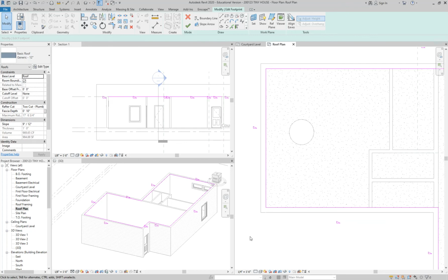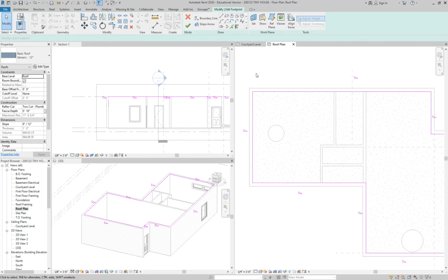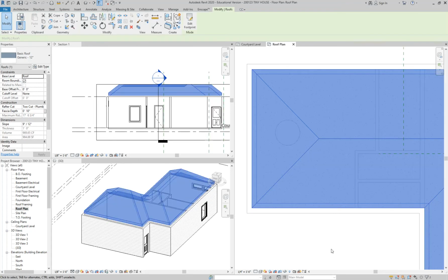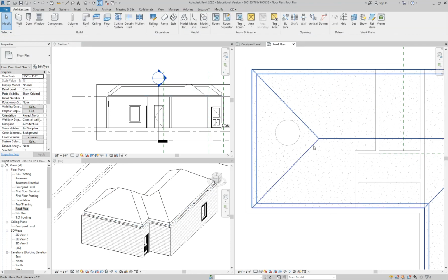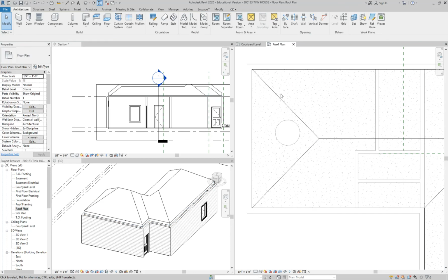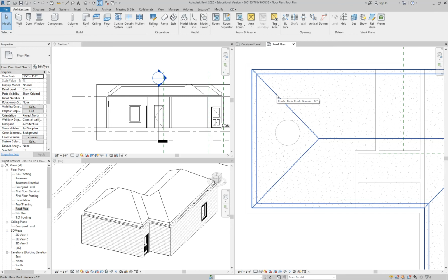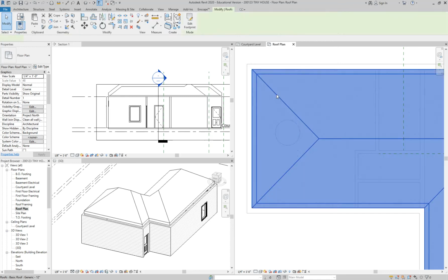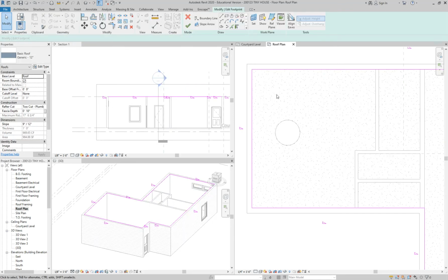Step, please. Which step? You clicked on the roof and then you did what? Edit Footprint. I'm going to show you both ways again. You still see your roof, you're not editing it yet. I've clicked on it, it's blue. The first way is to click on it and choose Edit Footprint. What's the easier way? Double click on your roof. We couldn't do that with our floor because floors are hard to select. Fundamentally we should, but they're just really hard to select.